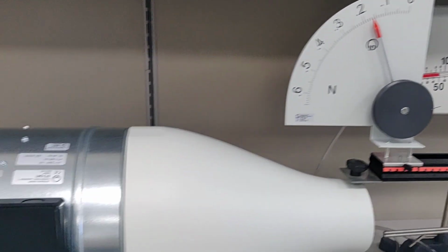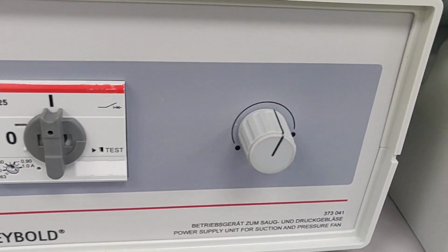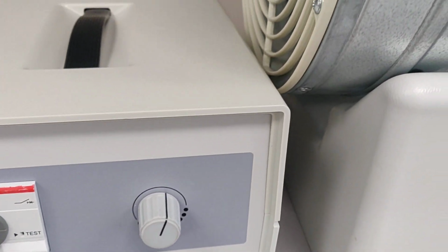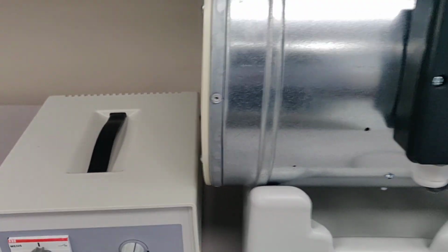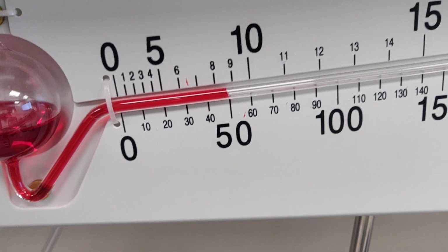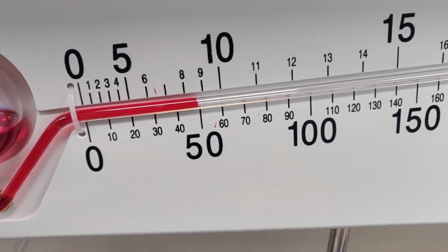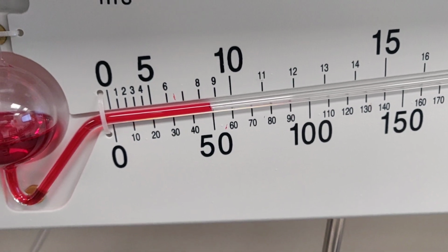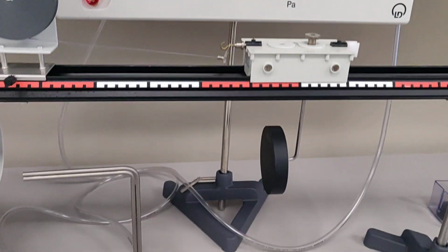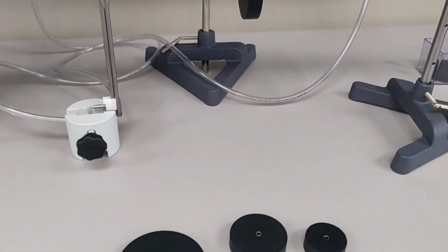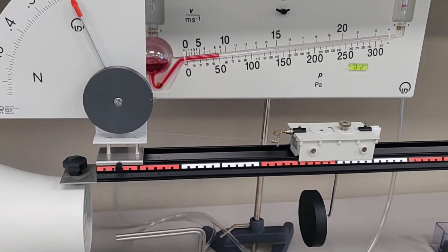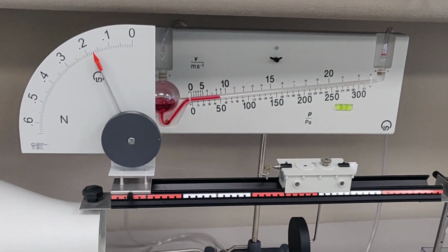For test number 2, you are going to increase the fan speed from here, move the roller to the right side. That increases the speed of the fan, so the air velocity will increase, the dynamic pressure will increase to some other value, maybe 60, maybe 30. You reduce the speed, it goes to 30, 20, 10. That way you can increase or decrease the dynamic pressure, and the velocity also changes. Each time you change the fan speed, you are going to measure the drag force F1, F2, F3 for the three discs, and that way you have to complete 5 tests for 5 different speeds of the fan.